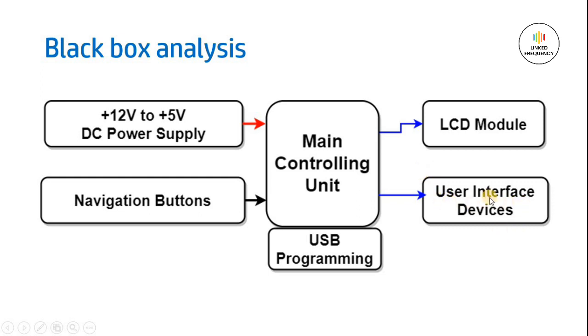This may be a simple buzzer and an RGB LED, not much more than that, because we want to have a feedback system for a human whenever they press the navigation button. For that reason, we need a buzzer and RGB LED just to indicate there is a signal which is received at the microcontroller from the button. Otherwise, they will keep on pressing until it reflects on the LCD display, which is very complicated when you consider user experience and user interface with respect to the embedded system.